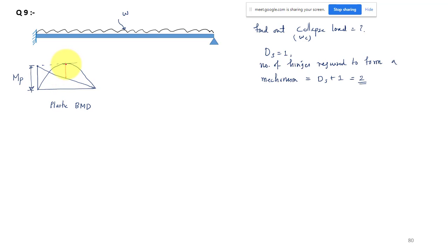But finally your net moment diagram is only this much. This is your negative moment, and this is the positive moment. This triangular part is going to get cancelled. Let me draw that in green color. This part is not there in your moment diagram, it just got cancelled, positive and negative. So your net moment diagram is only this white color. This part is the negative moment, and this is your sagging moment. So one maximum moment you can expect at the support.